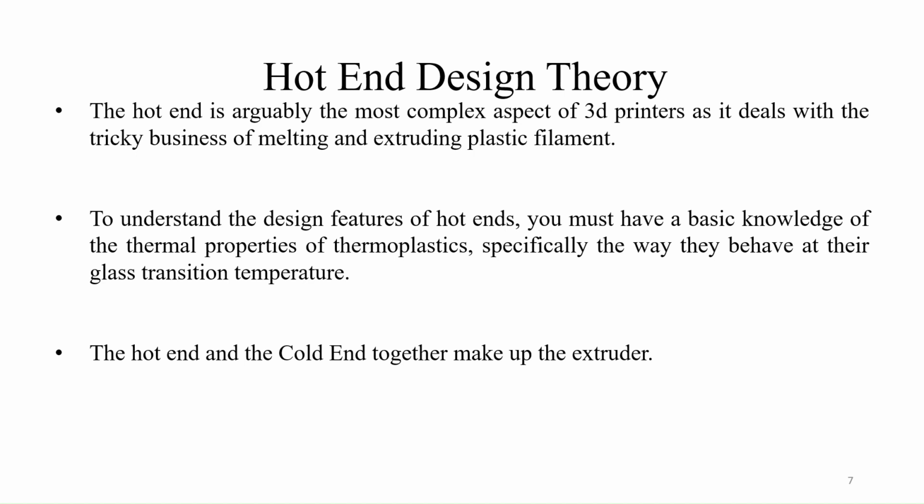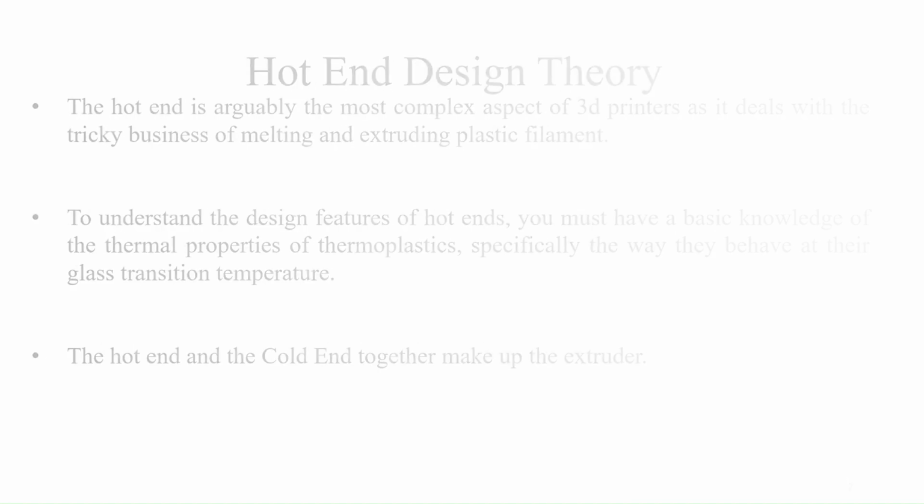The hotend and the cooling system together make up the 3D printer hotend block. The 3D printer heating block is the part of the extruder where the nozzle meets the thermal barrier tube. Contained within the heat block are also the heater cartridge and the thermocouple.